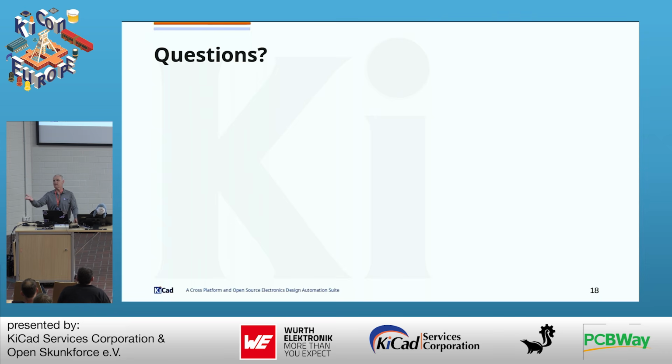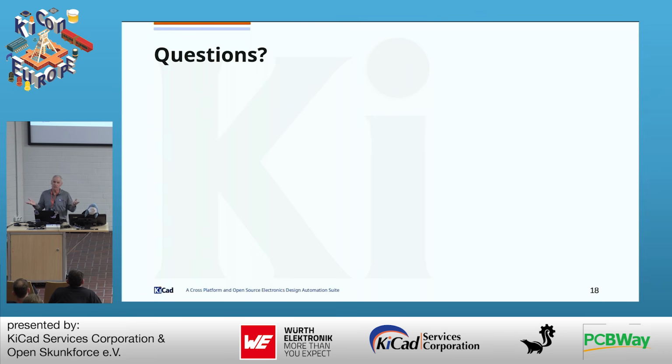Another example is you have a DIP-8 and then a SOIC-8. You can actually sit those inside of each other and map them 1 to 1. You can't populate both of those at the same time. It's one or the other, but you can have both footprints there and wire them up in parallel. That was one of the limitations with footprints: you can only have one at a time. But the copper pads of all the possible footprints will be present. So the board layout is the same, but only one of them is going to be populated.